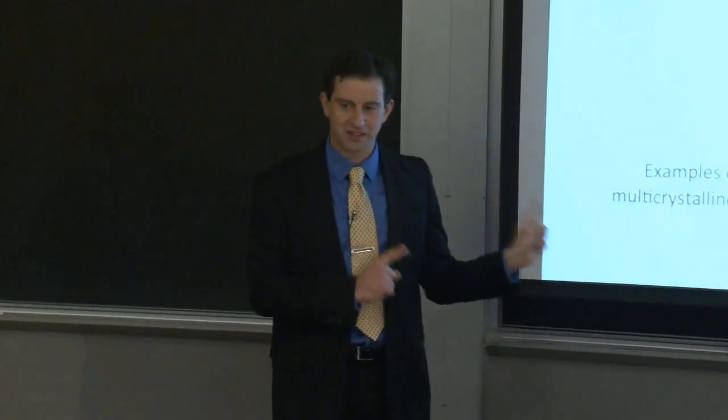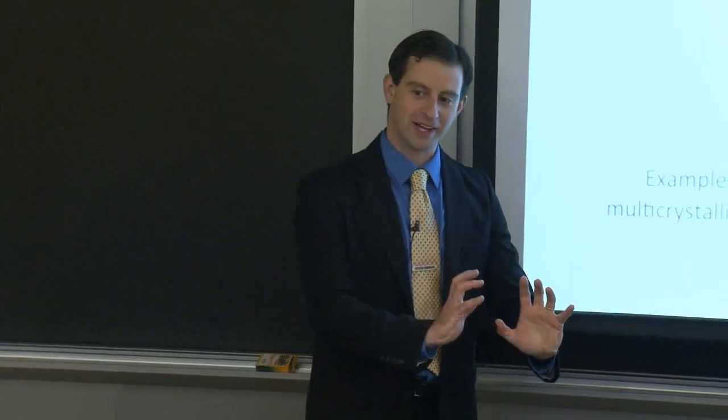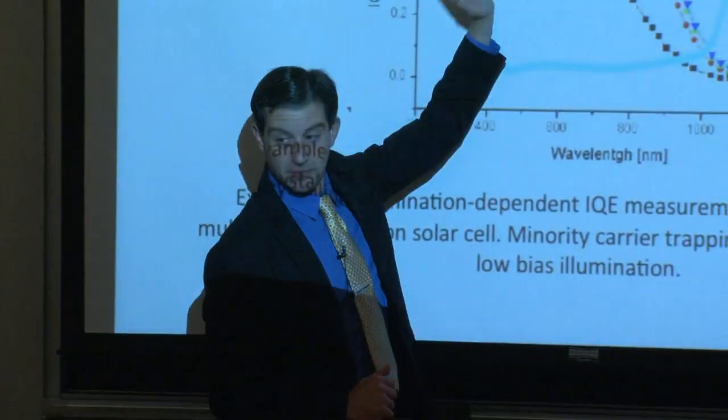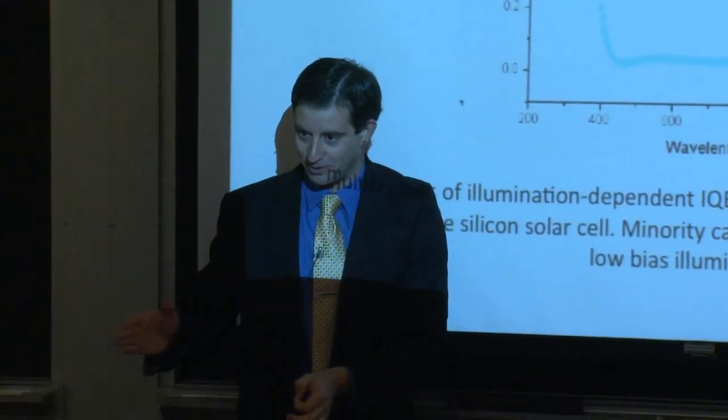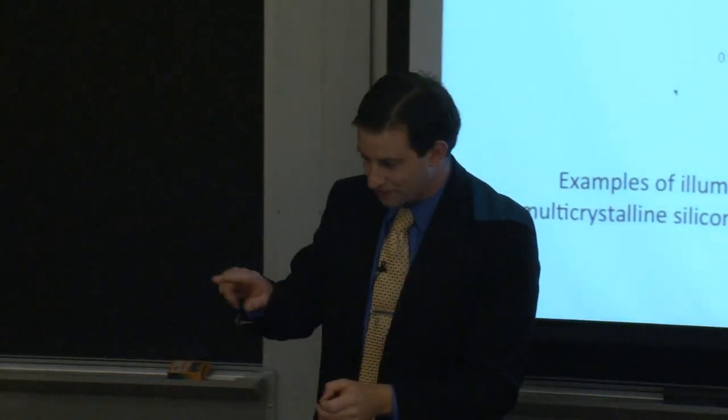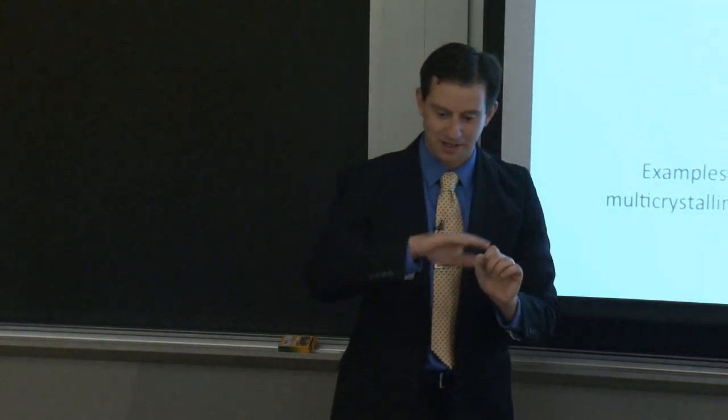And we ran the measurement in exactly those conditions. We had a steady state background light, and then we chopped the monochromator light coming in and used a lock-in amplifier to track that particular frequency. So we're able to detect the small perturbation due to the monochromatic light coming in on top of the steady background.